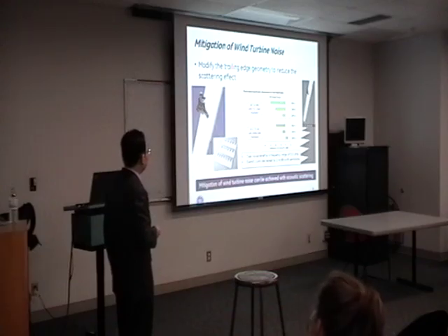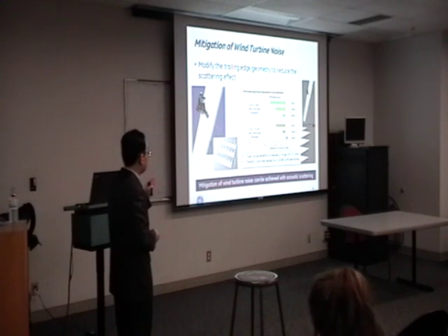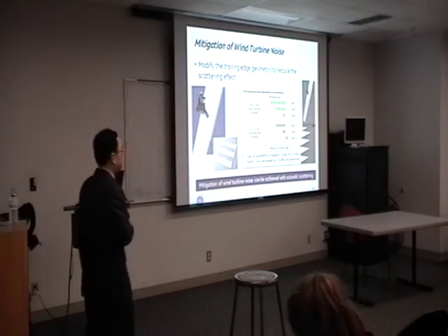So we tested a 1.5 megawatt turbine and also a 2.75 megawatt turbine at different frequencies: 500 Hz, 1 kHz, 2 kHz. And the value on the left is the noise reduction by this geometry. Here 0 means there is no change of the noise, a minus value is noise reduction, and a positive value is noise increase.